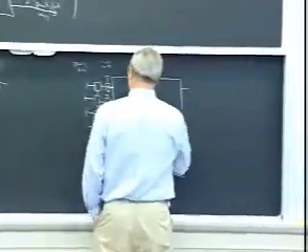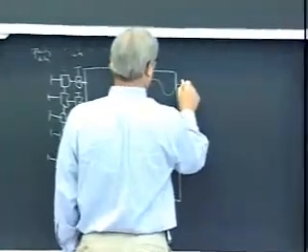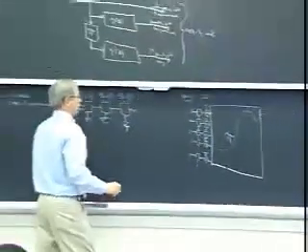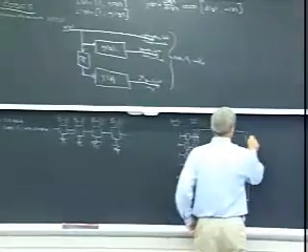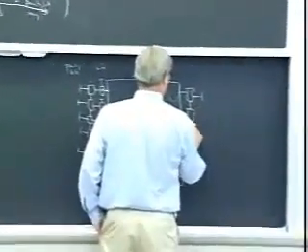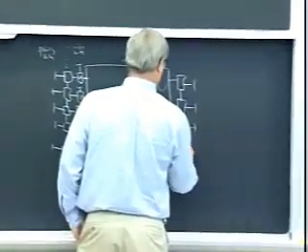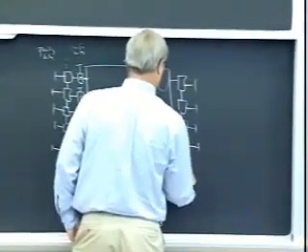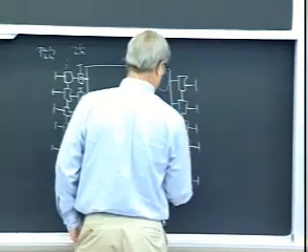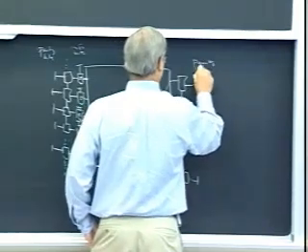Okay, after some huge permutation, they come out over here. And now these are information bits that go into another identical trellis, or could be identical. So we have a trellis over on this side that's connected to one parity bit and one information bit. It's another rate 1/2 trellis. This is parity bits.